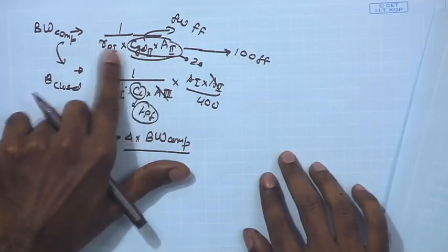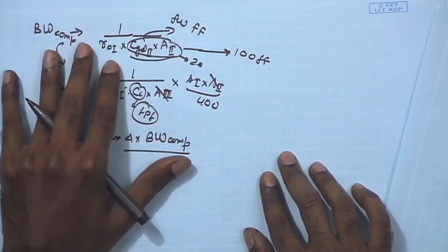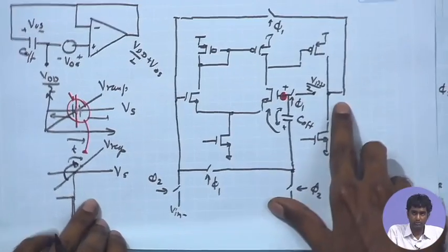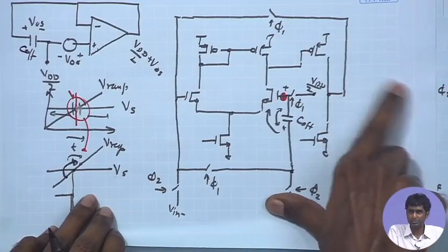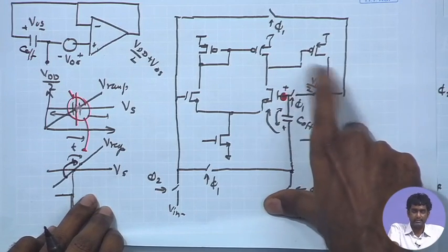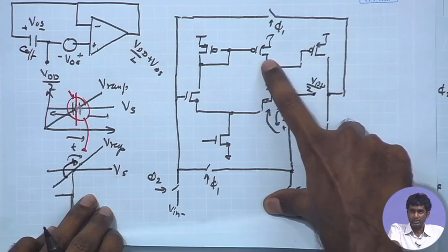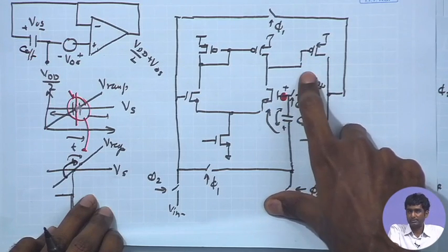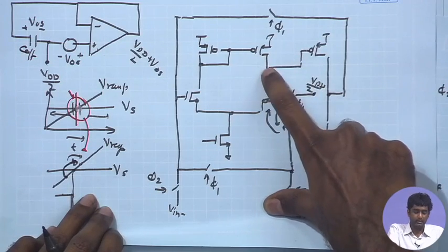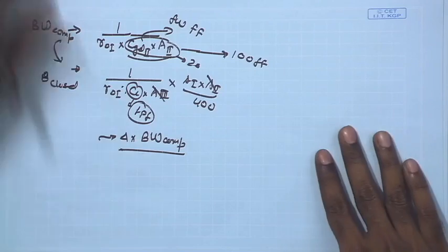I hope this point, how we determined the bandwidth in the comparator case, was clear, because there what we had assumed was that there is no significant load capacitance coming here, it may be just driving a CMOS inverter, therefore CL is small, just the parasitic capacitance of the gate, whereas in the second stage you have the CGD which multiplies and provides a larger load capacitance over here, and I assumed that to be the dominant pole, and hence estimated the bandwidth based on that node, and then I compared it with the closed loop. So, this is just a cross check on our assumption.